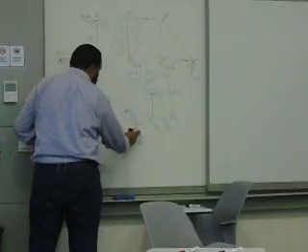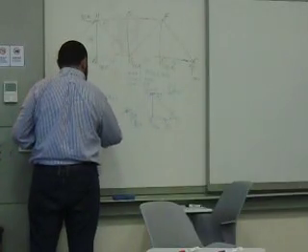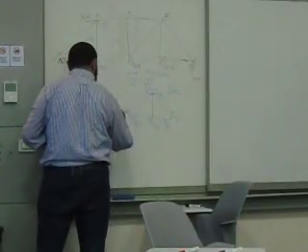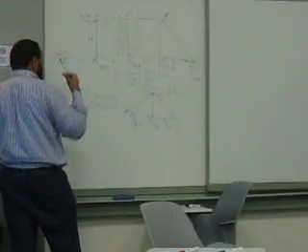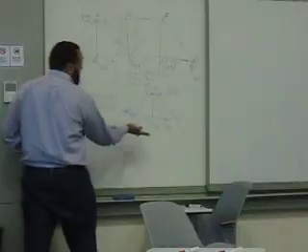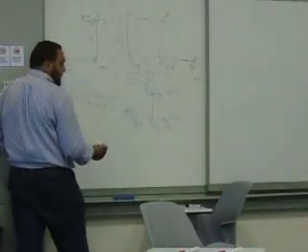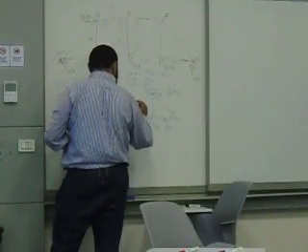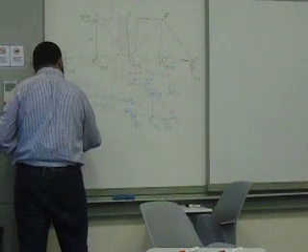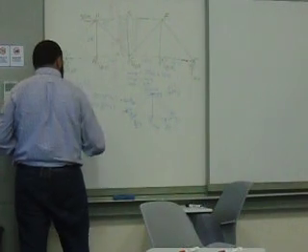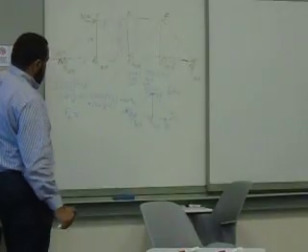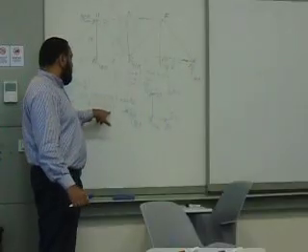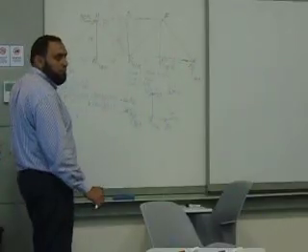In the positive direction, what is it? The 50 plus the 50 times the perpendicular distance, which is 15. In the negative direction, I'll have the unknown itself, FBC, times the R. So minus 20 FBC. Therefore, FBC, if somebody gets the number, is 20 times 30 plus 50 times 15, divided by 20.